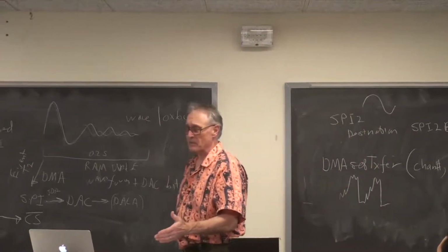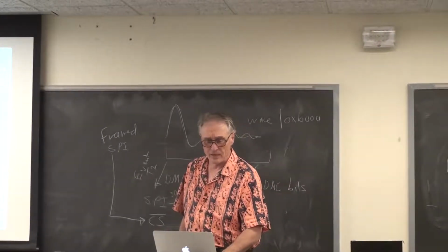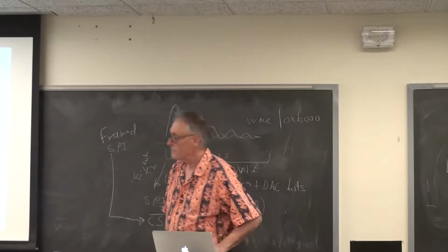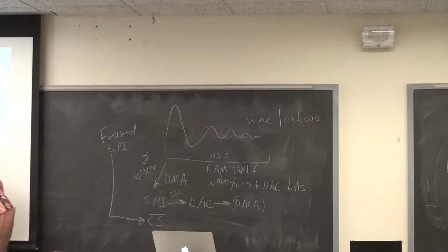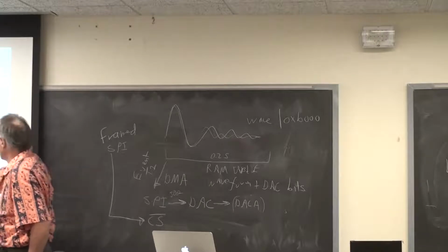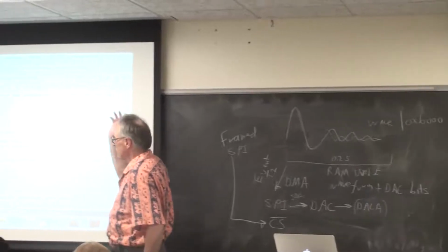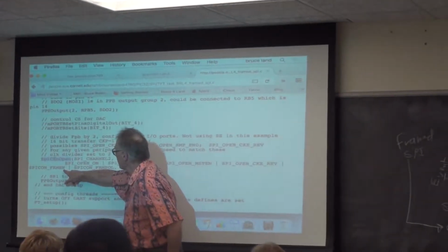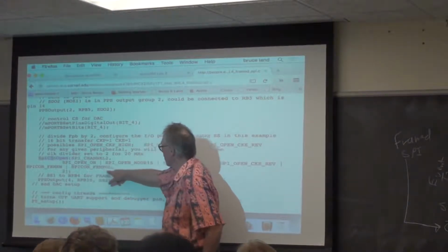It just happens. And the reason it just happens is when you do the SPI setup down here in main, when you do the SPI channel opening channel 2, mode 16 bits, master mode, clock enable, whatever it is, SPICON, framed, FRMEN, and FRMPOL.